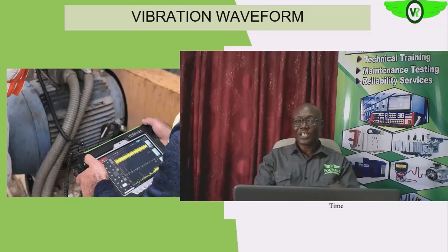And on each end of the shaft of the rotor, we have bearings. If we are looking at ball bearings, these balls, as they are rotating within the bearing race, both the inner and the outer bearing race, are also introducing some level of vibration.